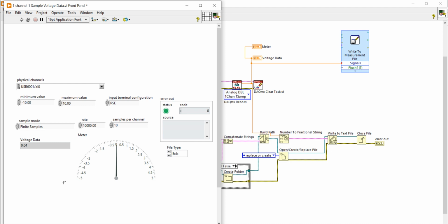See, dear system, you have to count 10,000 samples every second, and I will read the 10,000 samples, and get them ready for each channel. So the sampling rate is 10,000 hertz, and samples to read is 10 kilo. The sampling rate which I had fixed here is 10 kilohertz.